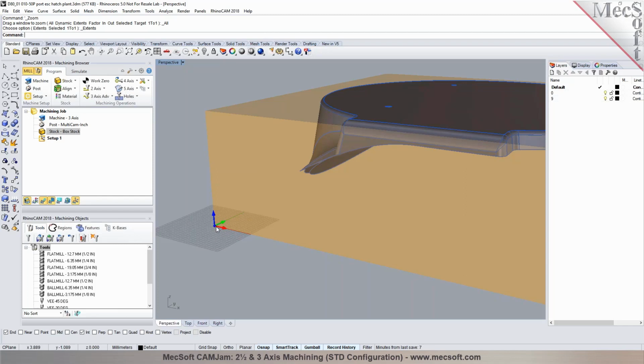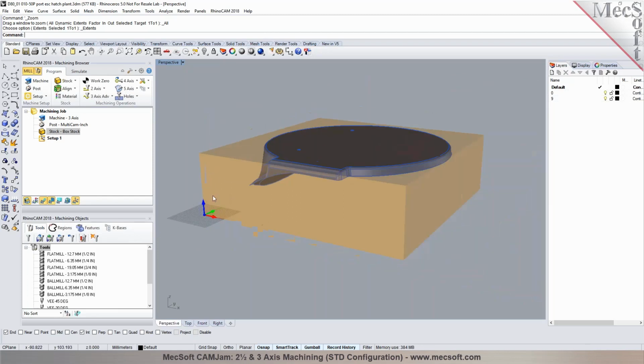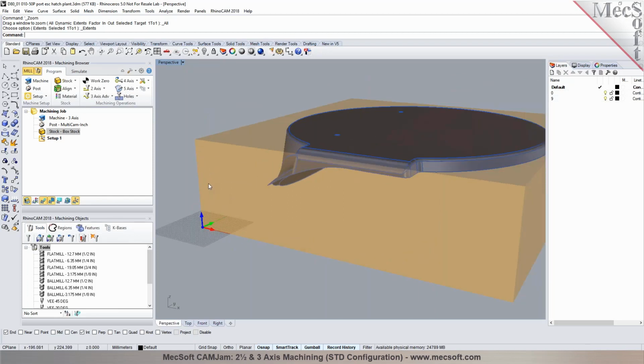So from the origin, as the cutter moves up, it's a negative move, and as the cutter moves down, it's a positive move. We do that scaling of the Z coordinates in the post-processor. Yeah. So right now you'll have a negative Z value when you post-process the code out, so you wouldn't probably be seeing any positive values for Z.